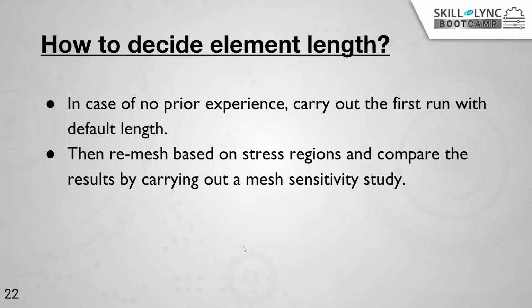So what is a mesh sensitivity study? You reduce the mesh size in every iteration till there comes a point when the difference in the results is not that much. That is called a mesh sensitivity study. When the analysis is very complex and it's a very critical component, it is always suggested to carry out a mesh sensitivity study, and chances are that the clients might even ask you to submit a mesh sensitivity report before they approve the results.